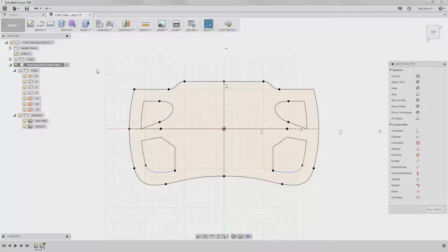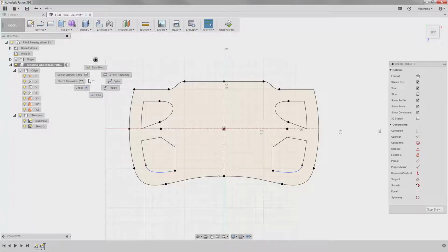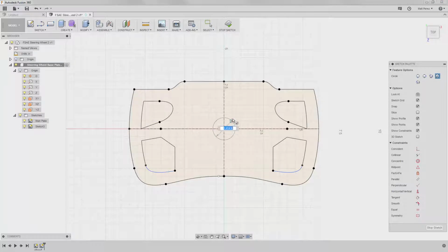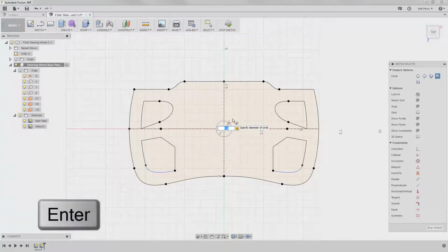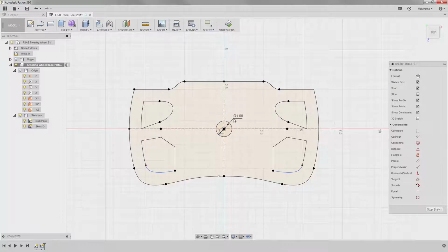Navigate to the Circle tool however you see comfortable. I'm going to right-click, go to my sketch, and up to Center Diameter Circle. Place it at the origin, and as we're sketching it and the diameter is displayed in blue, I'm going to press 1 on the keyboard and enter. Notice that now there's a lock icon to the right of this. Press enter again. This will OK the dimension for me. I can move the dimension at any point in time, but this saves us a step from having to manually apply the dimension after the fact.